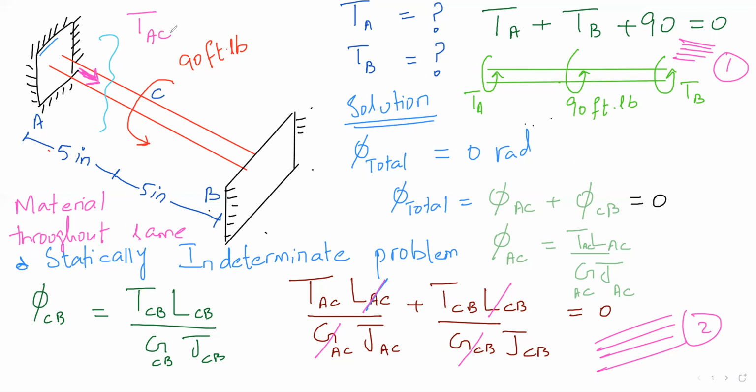I think when we are cutting it, after cutting, I will throw this chunk away. I think we will be looking from this side, no? So I will say TAC plus TA, because TA, if you remember, is nice and beautiful anti-clockwise. So TAC plus TA equal to 0, and TAC comes out to be negative TA.